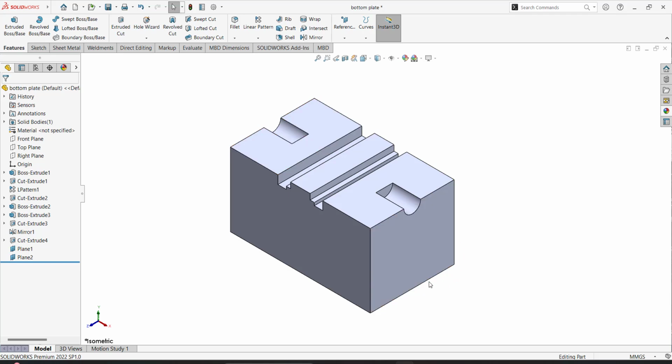The importance of isometric view is these two sides are adjacent and are at an angle of 120 degrees from each other. And the angle from the ground will be 30 degrees each. So the importance of isometric view is you can see all the three faces, front, top and side, and the features that are covering those faces. So it is very easy to understand or read the object by showing all the three sides by arranging them in isometric view.